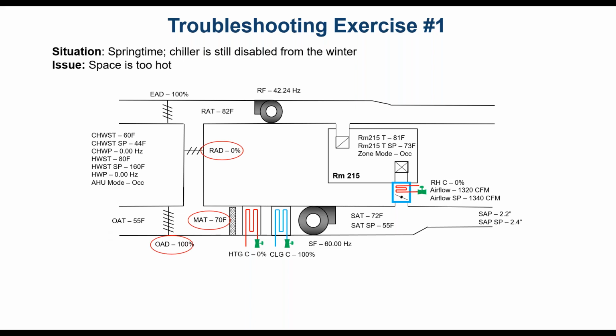But we're finding 70 degrees Fahrenheit. I think we're onto something here. I think we might have found a potential issue. The damper positions are not where they're commanded to be.